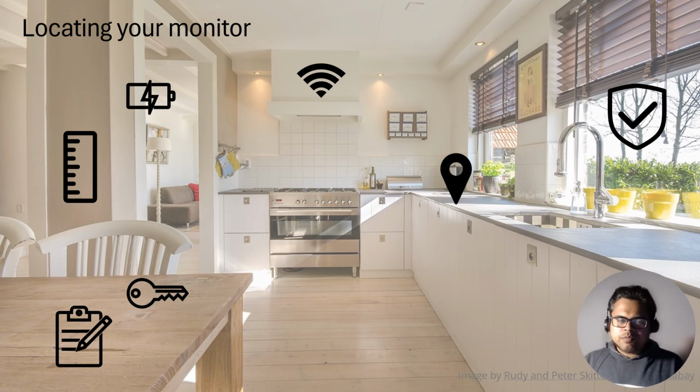When you deploy your monitor, there are a few things that you need to be careful about. Location of the monitor, as in which building and which floor you want to place it. Placement of the monitor, as in at what height or how far from windows. Generally, you want the sensor around breathing height of people, far from windows, doors, and ventilation outlets, and not too close to people so that they don't directly breathe upon it, as that would affect the temperature and CO2 readings.